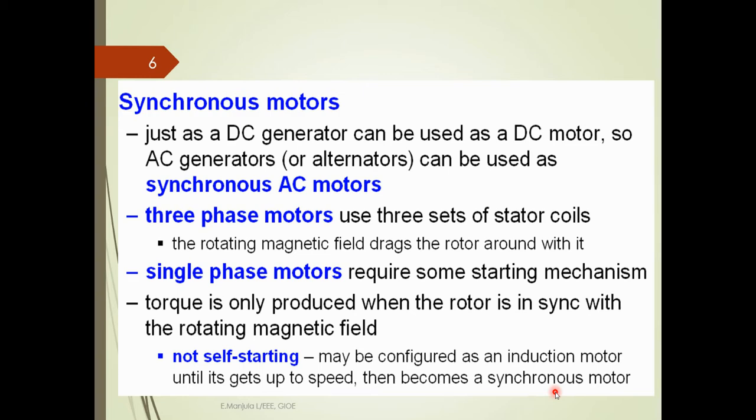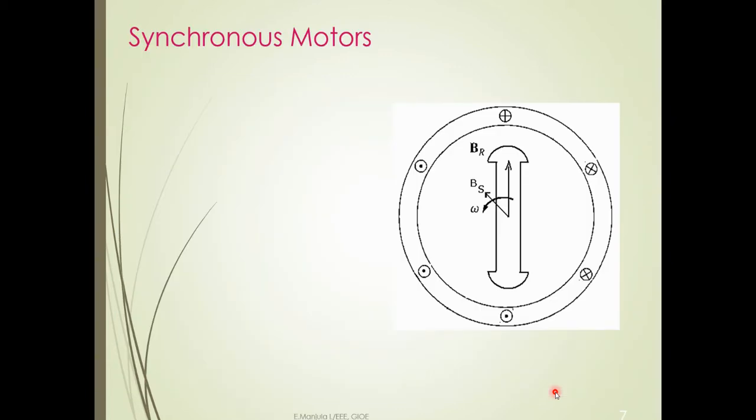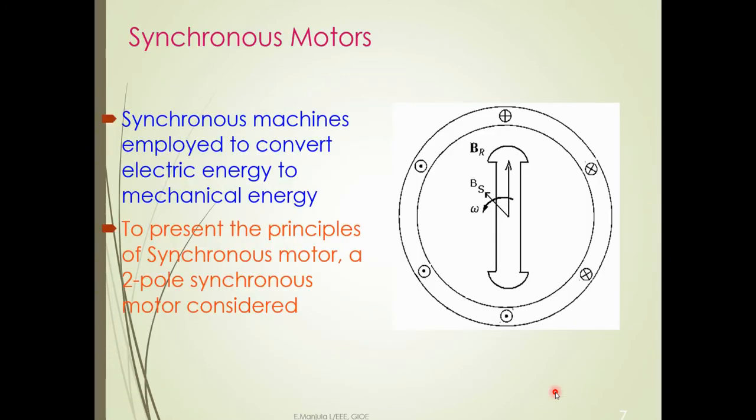There are some starting methods. Here we run it as an induction motor to some extent. After attaining a certain speed, we remove the induction motor topology, and then it runs as a synchronous motor. So this is a synchronous motor, the stator, and here we have the rotor.